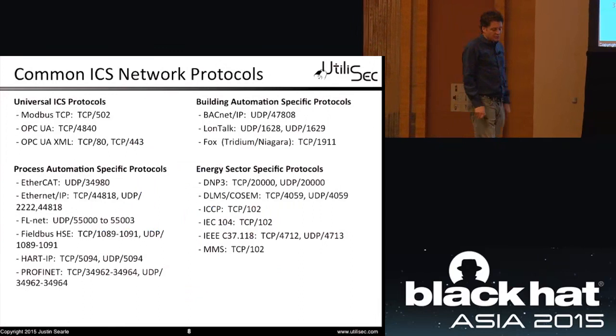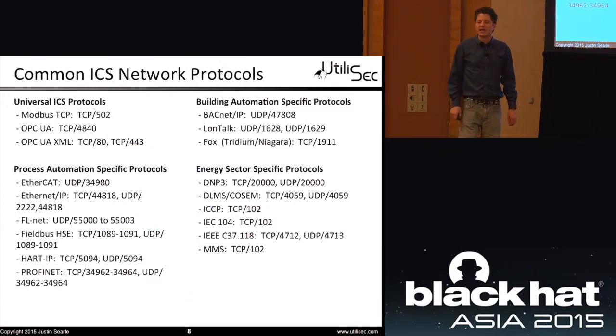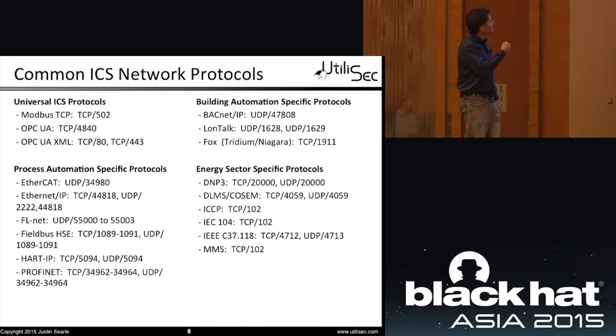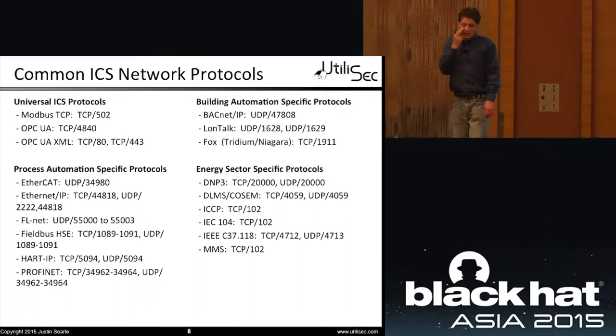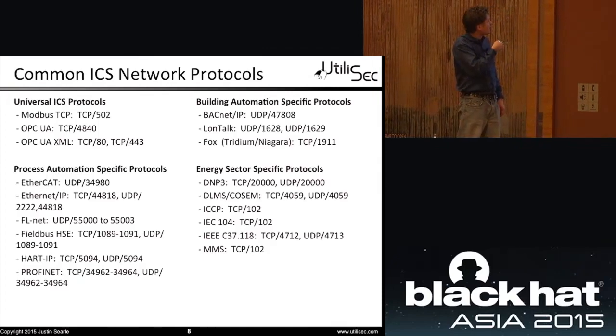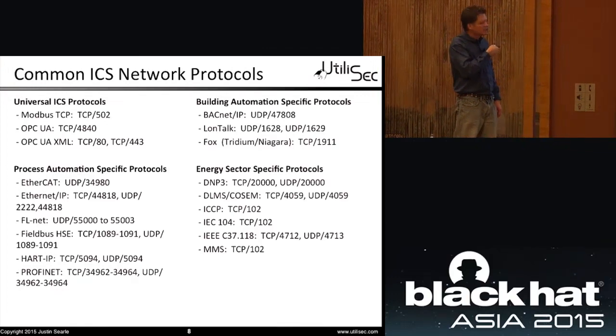Now, there are other protocols besides Modbus. If you want a list of some of the major protocols that we have in control networks, here's a fairly succinct list of the most popular protocols you'll come across inside of our system. Notice that Modbus and OPC are two very common ones. They work at different levels. Modbus is down on the PLC level. OPC is a protocol that we often speak up at the HMIs and the master servers, higher up the communication architecture. So those are some we have in our manufacturing.